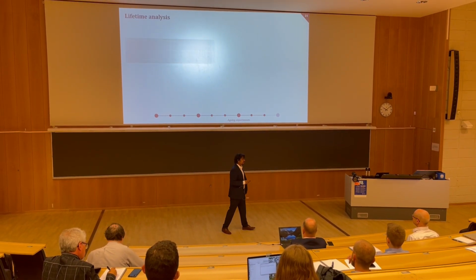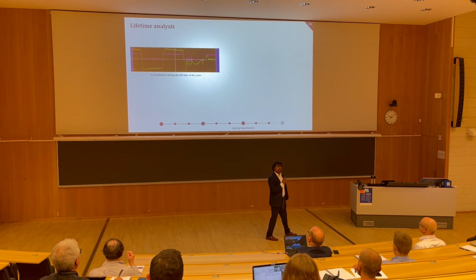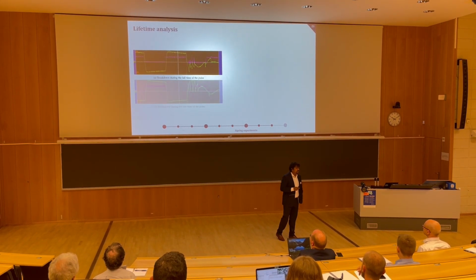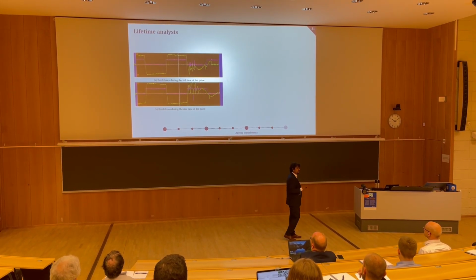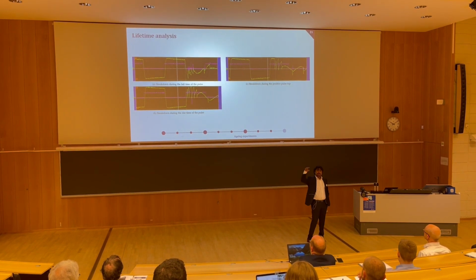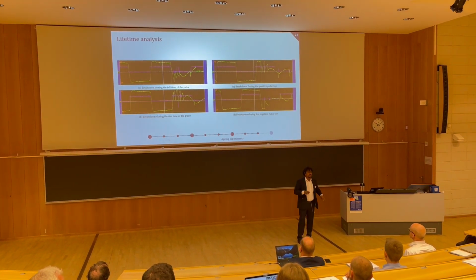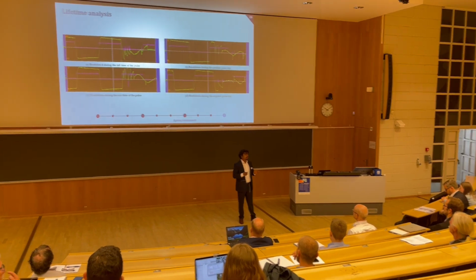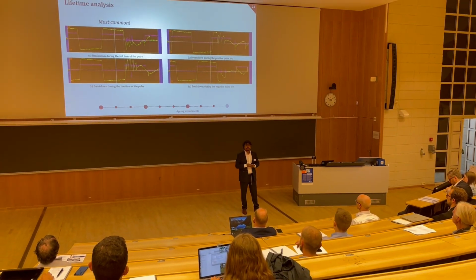Also, the last interesting thing that we see is where exactly did this breakdown happen? So we had breakdowns during the fall time, the rise time, the positive pulse stop of the pulse, as well as the negative pulse stop. But the most common was during the fall time.